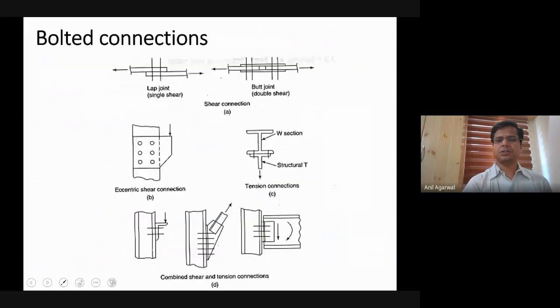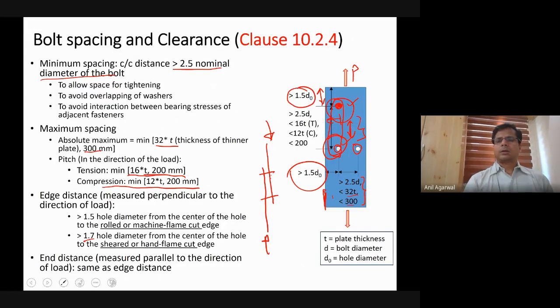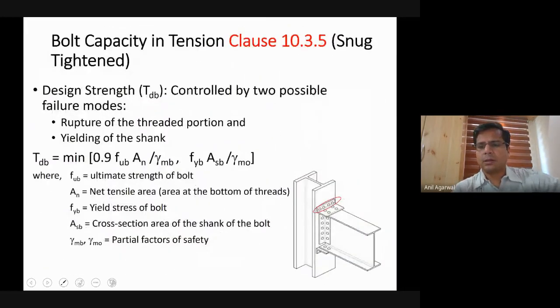And you may have various conditions where the bolts are undergoing a combination of tension and shear. This is combined tension and shear. All these bolts are similar conditions. Okay. So the image that I've shown here, unless this beam here is being pulled in the actual direction, in that case you would have direct tension in these bolts.